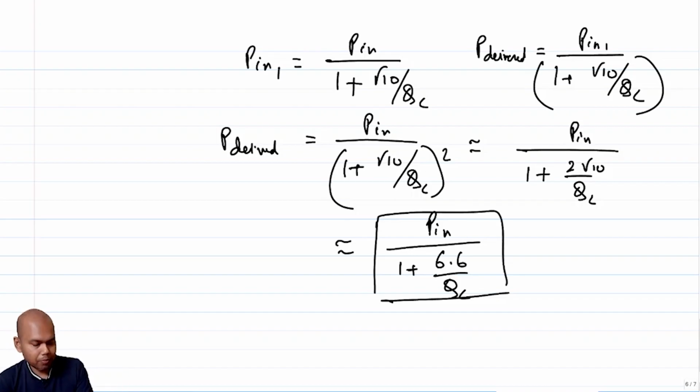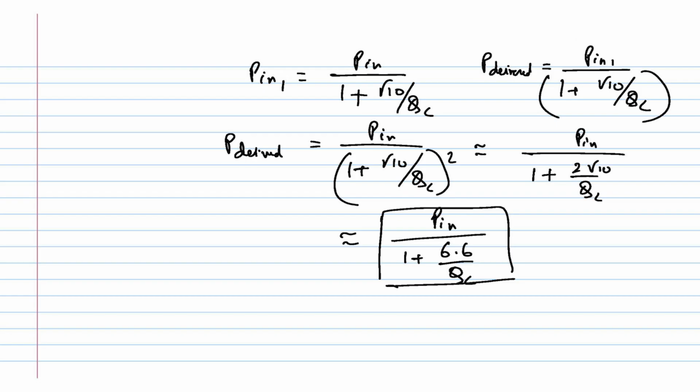But the problem with that is, naturally you would end up using many components, which means the area becomes a problem, right? So that becomes a design choice as to whether you would like to have that, whether you have that area to be used or not. If you have sufficient area and you also want this large transformation of resistances, then for a given value of QC, it is always better to get to multi-stage. I showed you for 2-stage, obviously you can extend it to many more stages, right?